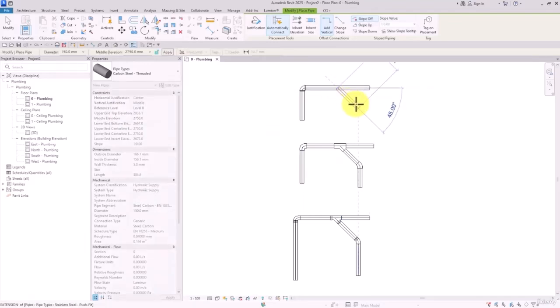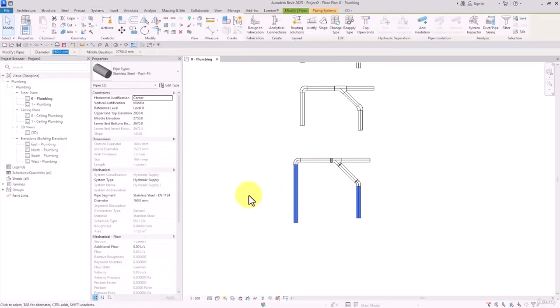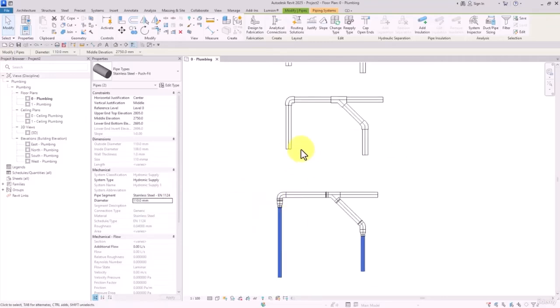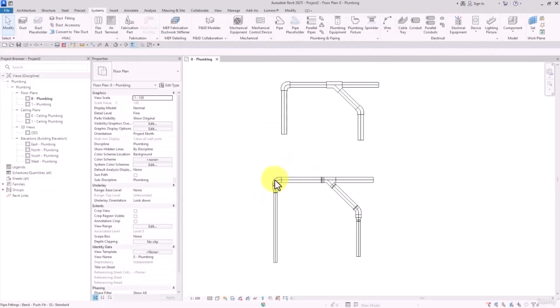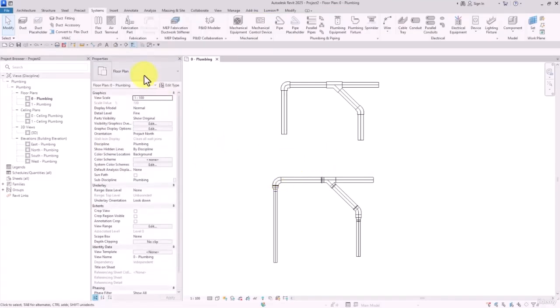And then it's sketch. And basically, this is what Type Selector does for us. Now, from instance properties, you can go through some settings regarding the selected object in your viewport. So again, only the selected object. For example, if I change the diameter here, only the diameter of the selected object would change. Or as another example, if I change the fitting here, this would happen.